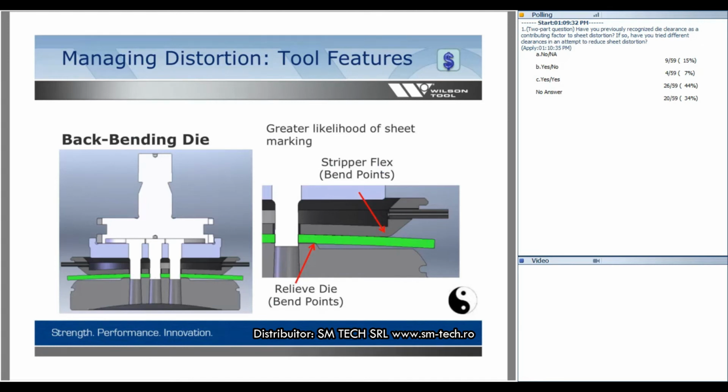But when we go down that road and you sharpen it, now you're changing the condition more drastically than this approach where we're using a flat top die. We're relieving the sidewalls, creating a pivot point. There you can sharpen it without really changing the outcome very much at all. All you have to deal with is that bend point on the die. You want to make sure you get a nice soft radius on that when you're done sharpening it. But, hey, we're backbending, we're creating these pivot points.